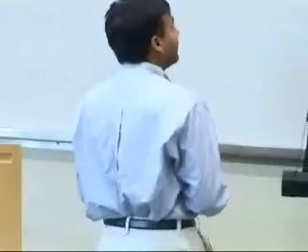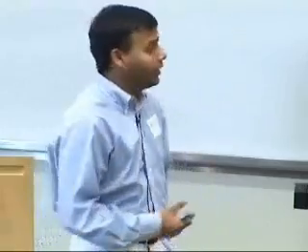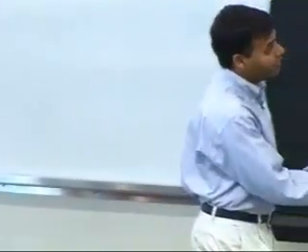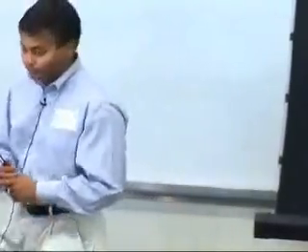And as long as you can find delay shifts, you can tell whether there is something wrong going on in your system before the system fails. Okay, so that's kind of the key idea over here. Now, as I said, for transistor aging, it's pretty well established how these delay shifts happen, and these are positive delay shifts. Things get slow, basically. But for early life failures, like for example gate oxide problems, we have actual experimental data, and we are clearly saying that delay shifts can happen in both directions before the chip absolutely fails. But still there are delay shifts, and if you can find delay shifts, you should be able to find whether there is a problem, and this can provide even several different kinds of alternatives to burn-in.